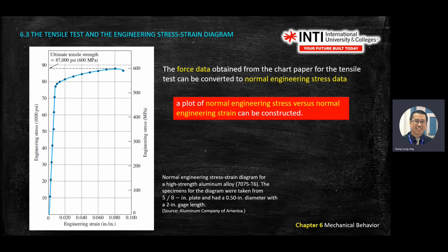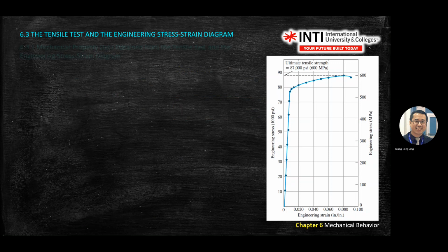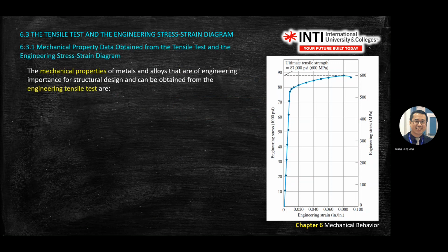From this experiment, you find the E for the material, then you compare back to the textbook values that you have. If you're given an aluminum rod, refer to aluminum, then discuss why the value is different. The rest you read.